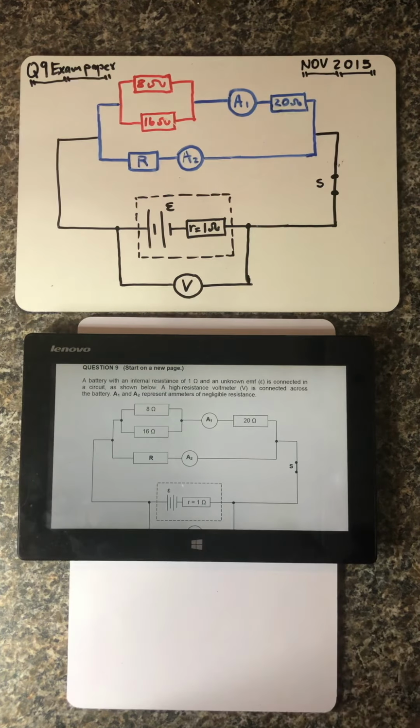So it's going to be this ammeter there and R4 there. So this is R4, then this is R1 plus R2, okay. Then we have R3 there, we've got ammeter 2 there, okay. So this is R3. So guys, I'm just showing you how to convert this branch into a series connection. So this is how it looks.